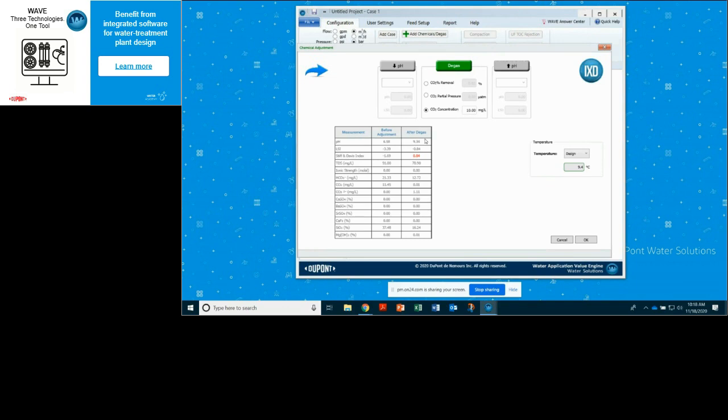degasification. When you specify a CO2 concentration, in this case 10 ppm, you're specifying the total amount of CO2, bicarbonate, and carbonate in the water. If you look at our starting water, we have a lot of CO2, but we also had a lot of bicarbonate, and this bicarbonate is being used to help charge balance the water. If I take out too much CO2, if I try to take out all of this CO2, I still have most of this bicarbonate here for charge balancing.